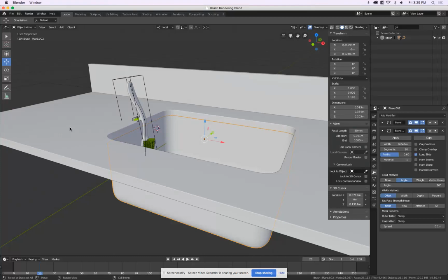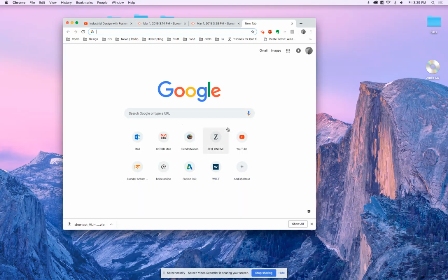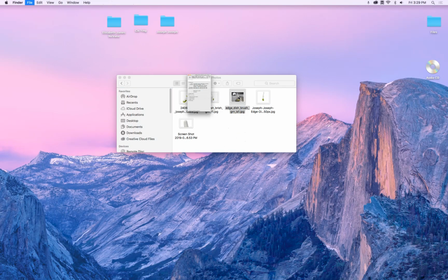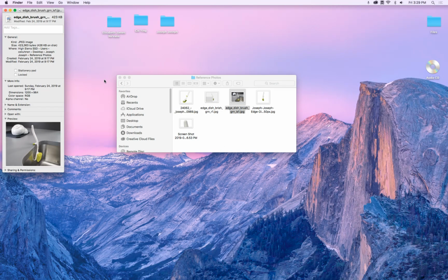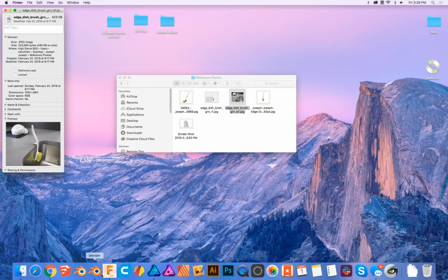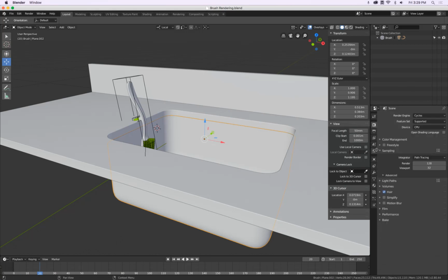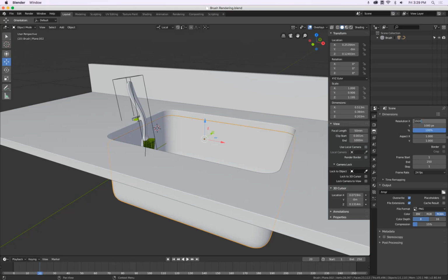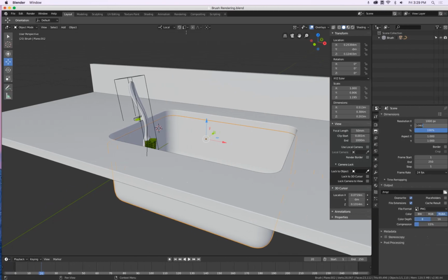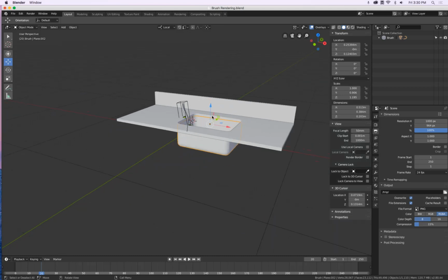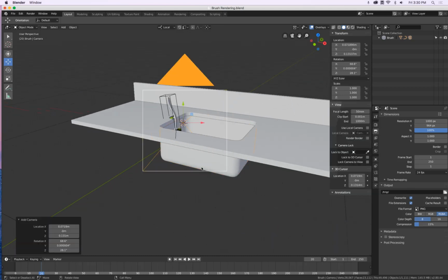To match the camera to this image, first we want to see how big that image is. So it's 1200 by 964. So in Blender, we go to rendering and our document is 1000 by 968, 964. Okay, so now when we make a camera, Shift A, camera,